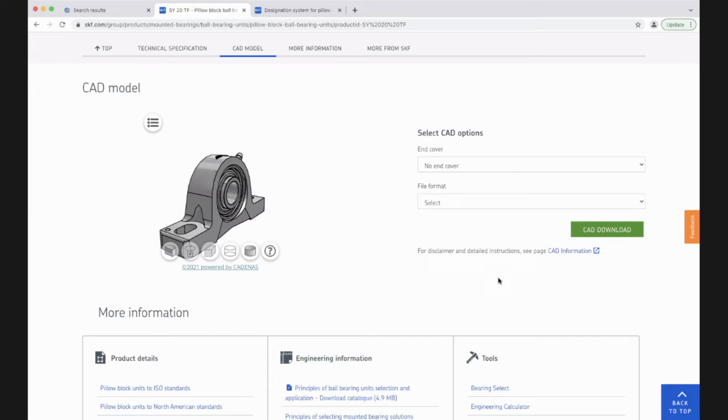So then that's, as we talked about on Tuesday, in reality, you'd want to think about thermal expansion and whether it wants to be located at both ends or whether it can float. If you don't know what I'm talking about, you can go back and look at the lecture somewhere in the middle where we talked about that for a few minutes. But the idea is just that you don't want, if any expansion happens, for the shaft to be trying to expand against two bearings that are holding it in place.